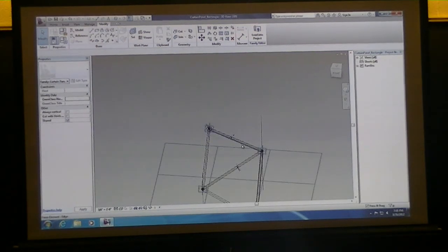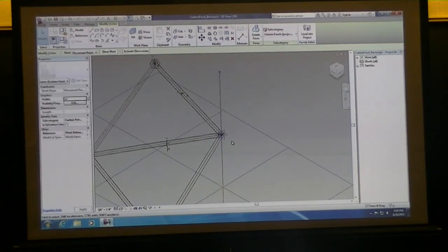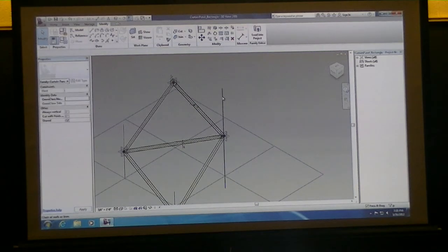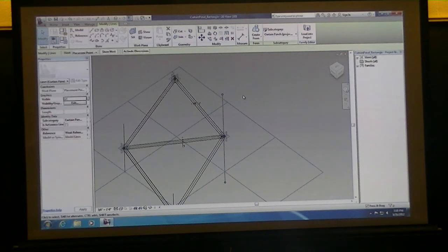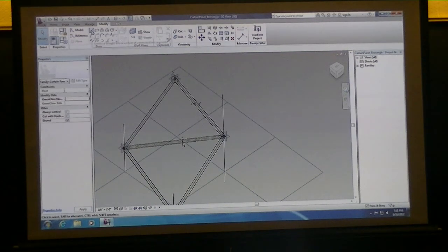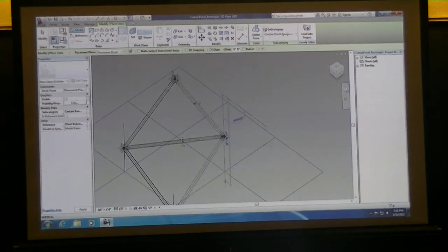Okay, so here's what you gotta do. Everyone should have gotten an error that's something about self-intersecting. That's because even though when you click on this line, it's actually still 2 lines, and for some reason Revit doesn't like that. So all I did was a workaround real quick: I drew another line and I snapped to the endpoints.